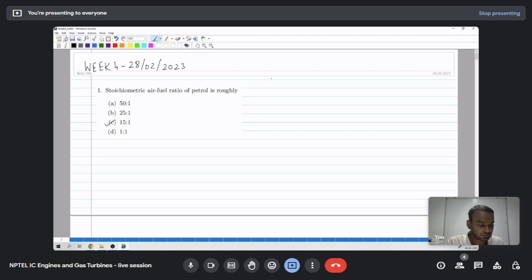So the fuel-air ratio that is chemically correct. Yes. So if we have, say, methane as a fuel, and then we have oxygen, where the oxygen will always have 3.73 parts of nitrogen because this constitutes air.